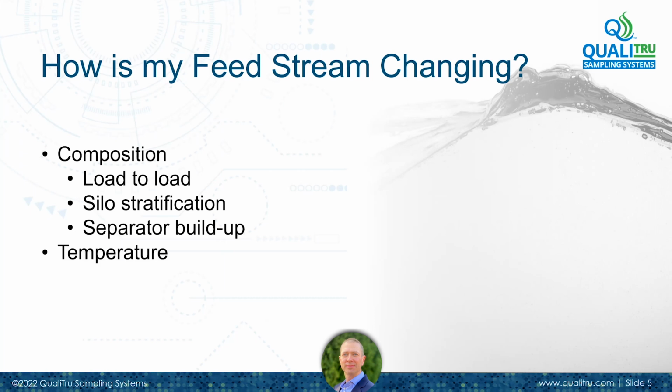Temperature is a big one. As elements foul, the permeation is slower, so there's more loops around the stage, there's more friction. And we've seen stage coolers right sized, but just not be able to pull out enough heat towards the end of runs. And that really changes the response of your system.